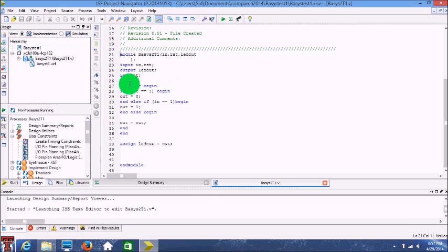So what this does is it's got an in for input, a reset, and the output that goes to the LED. I've also declared a register which stores the output value, and the output is directly taken from this register. I have a habit of doing this because if you have your output inside a loop or inside an if statement, Xilinx won't let you synthesize the code because it's a variable. So in that case, you need to add a register and then put that register in the loop.